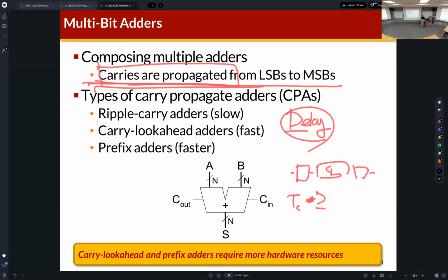But the propagation delay of this combinational logic is also included, right? And the delay of combinational logic occupies a large portion of this delay. Usually the setup time or clock skew is small, so the propagation delay of this combinational logic occupies the larger portion.